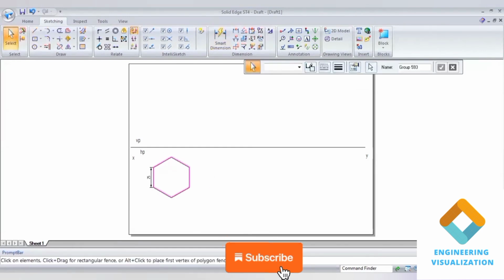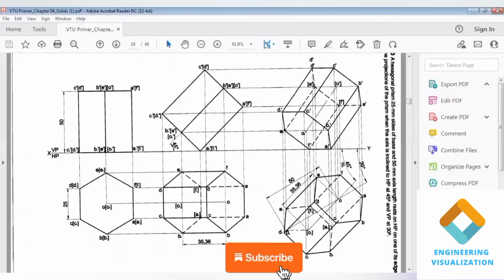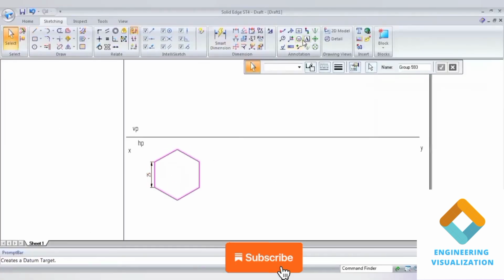Now write the top view and bottom view notations. Top view notations are written with A, B, C, D, and bottom face notations are written A1, B1, C1 like that, but they should be written within brackets.